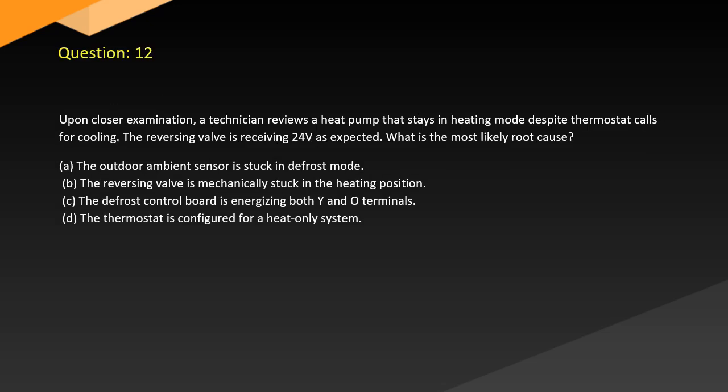Question 12. Upon closer examination, a technician reviews a heat pump that stays in heating mode despite thermostat calls for cooling. The reversing valve is receiving 24 volts as expected. What is the most likely root cause? A. The outdoor ambient sensor is stuck in defrost mode. B. The reversing valve is mechanically stuck in the heating position. C. The defrost control board is energizing both Y and O terminals. D. The thermostat is configured for a heat-only system.